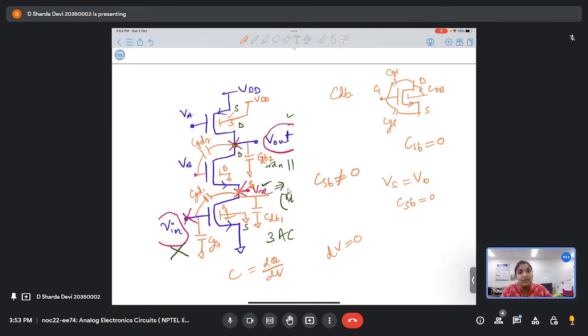There is a possibility that your transistor is in cutoff and you will get that point to be, let's say, VDD or ground. There is a chance. But you can never say. These nodes become floating. So when that is the case, these types of issues come into the picture. That is what I wanted to mention. Okay, so let's consider the body-grounded case, and for PMOSes it is connected to VDD, because it is a more realistic picture when we go for IC designing.